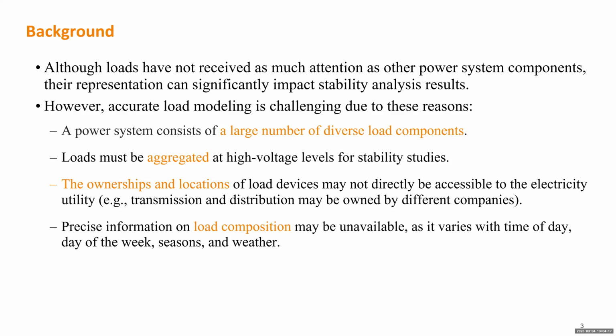So precise information on the load composition may be unavailable, especially since such a composition may change over time. For instance, even for the same substation, the winter load and summer load can be very different. In some northern regions in the winter, a lot of loads will be heater loads.